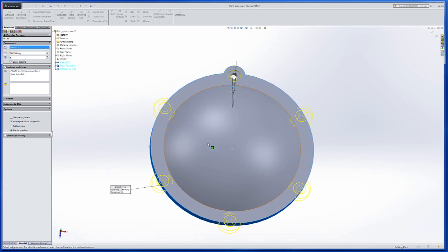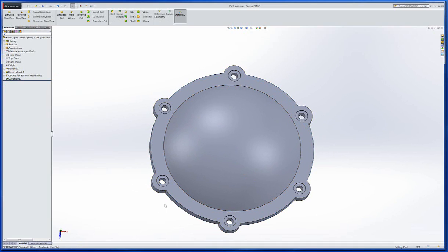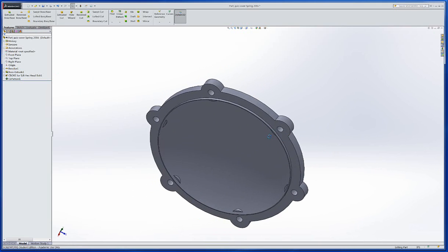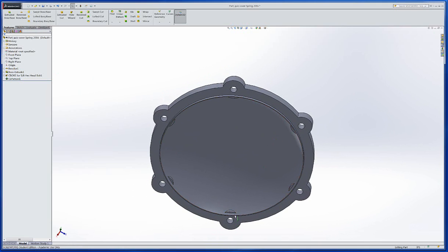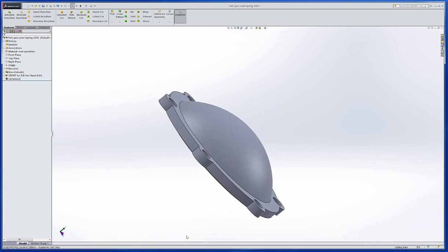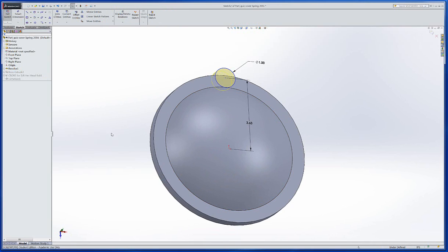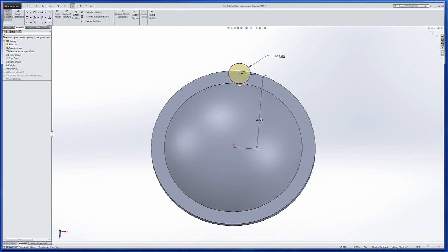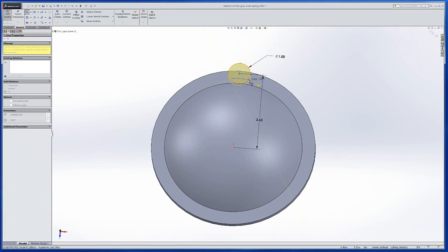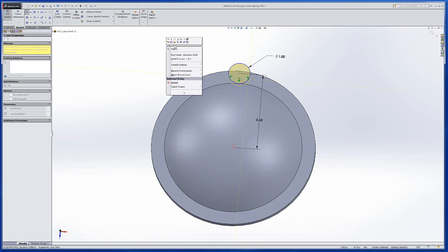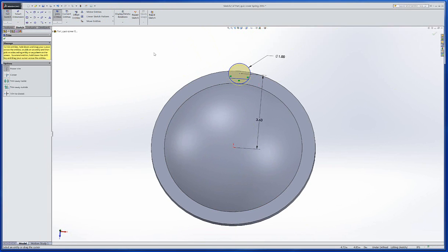Yeah, I've got to do some work on this, but I'll go ahead and create that. But it looks like there might be, yeah, see, there's some on the inside there. So what I'm gonna have to do is go back to this original boss, edit the sketch, and I'll go in there and draw a line just anywhere in there, and then trim that out there.